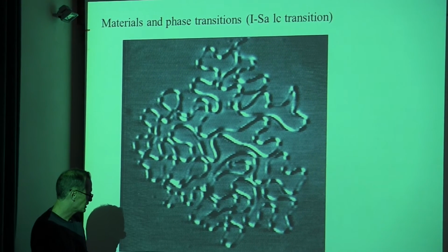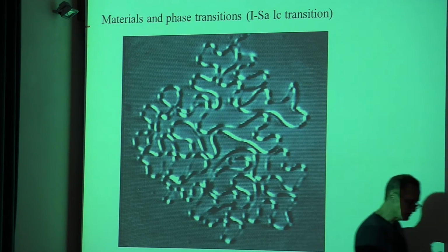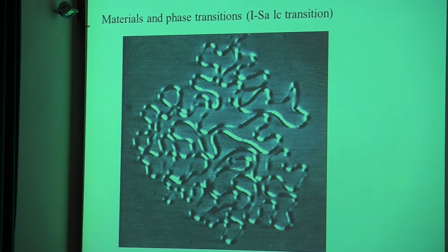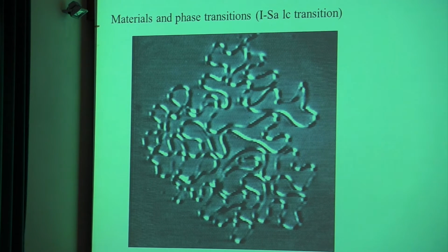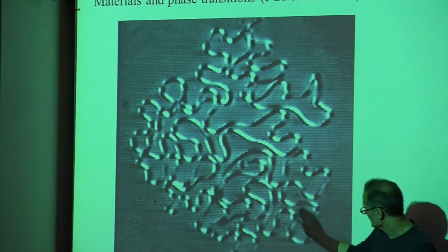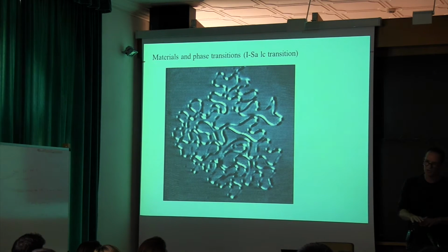And this is a picture through a microscope of a pattern that forms because I have a liquid crystalline fluid, which is, say, if it's warm, okay, it's in an isotropic state, it behaves like a regular Newtonian fluid. But if I start to cool it, it goes through a phase transition. And how many people in here know what a smectic phase is for a liquid crystalline material? Okay, a lot of you do. So those who don't, you can ask the person next to you and they'll tell you what it is. So what's going on here is that this has been undercooled, and so it's below this phase transition temperature, and it wants to move from being isotropic to smectic.